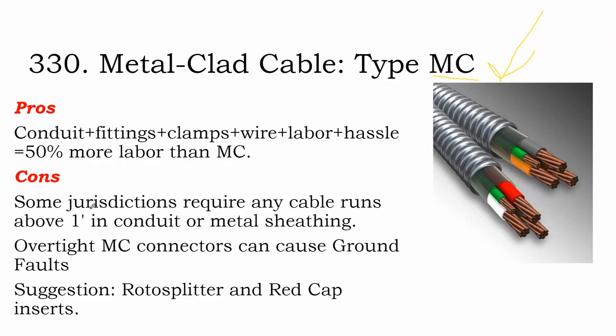Some jurisdictions don't let you use this. And I'd say if you're in a major city on the east or the west coast, multi-unit building, they might have a requirement to say, no, we want you to use conduit that's a little bit stronger than this metal clad cable.